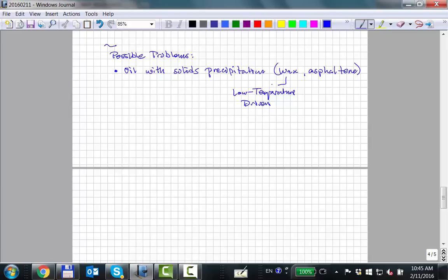You see this wax sticking to the walls or something, and you think, oh, the material we collect has too little of these C20 to C80 normal paraffins. But in fact, you usually get excess, too much of the wax paraffin. Somewhere or another in the sampling procedure, you suck in this excess wax precipitate. So the samples that you collect are too waxy.